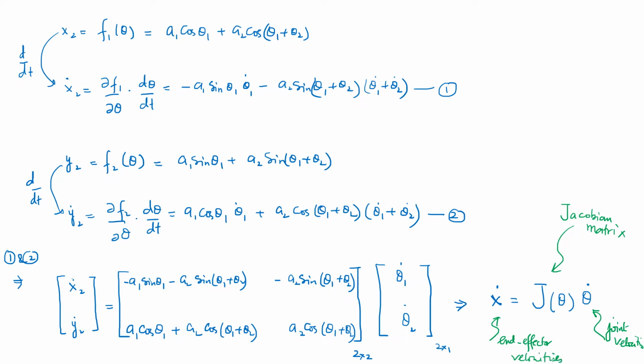So you can identify that the end effector velocities are related to the joint velocities using the Jacobian matrix in the middle. This expression is going to become much handier later on as well, and we will see how these Jacobian matrices are derived, and how we correlate what is going to happen with the end effector velocities when you know the instantaneous joint velocities. You would use this expression frequently, and this is what we call forward velocity kinematics. This is one part of differential kinematics.